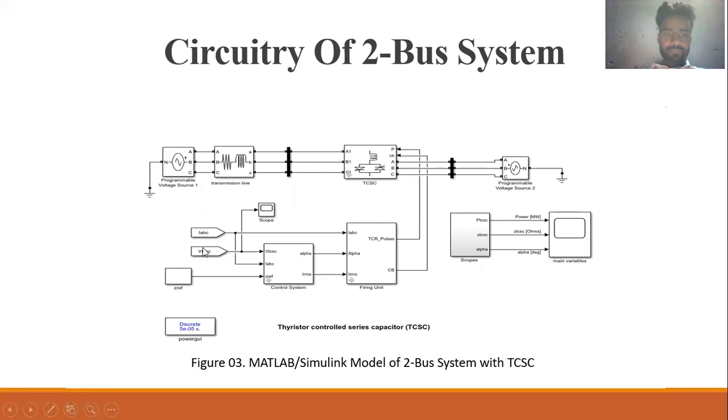So this is the current voltage and current that we are getting, it's measured, and we are providing its user reference. So basically by performing some control action of the PI controller, it's then fed to the firing unit, generating TCR pulses.